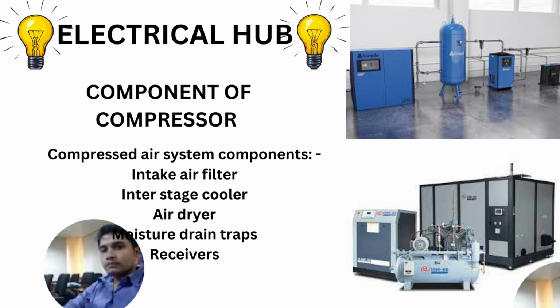Next is the air dryer. Air dryer is used to dry the air and remove the moisture, so that it can be used for pneumatic tools like control valves. Moisture drain traps are used to remove the moisture collected by the air dryer and the air receiver.